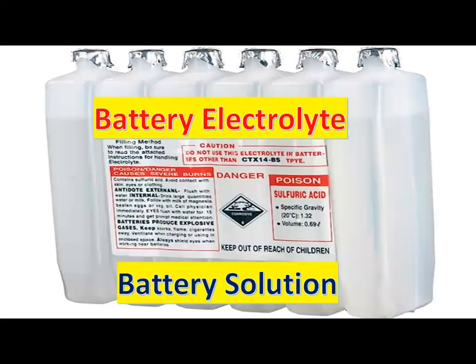Actually, you don't have to mix the distilled water and the sulfuric acid to make battery electrolyte. You can also purchase ready-made battery electrolyte that can be readily poured into the battery, and it already has a specific gravity of 1.32. Battery electrolyte is also called battery solution. It is very damaging to vehicle paint surfaces, upholstery, and clothing. Never allow electrolyte to contact any of these items.